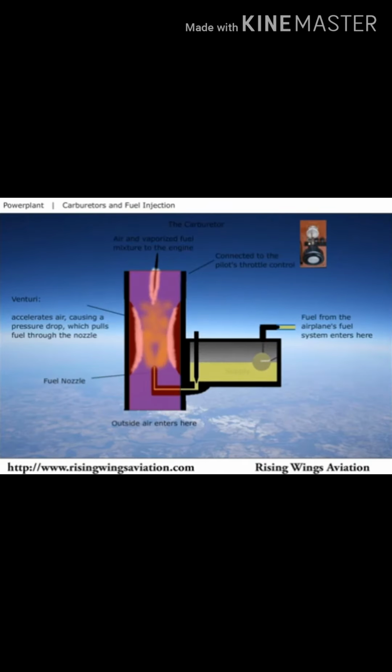The use of carburetor heat will also cause an engine performance decrease. This is due to the air being thinned as a result of being heated. However, it must be used to counteract carburetor ice, since continued ice formation will further reduce engine performance.